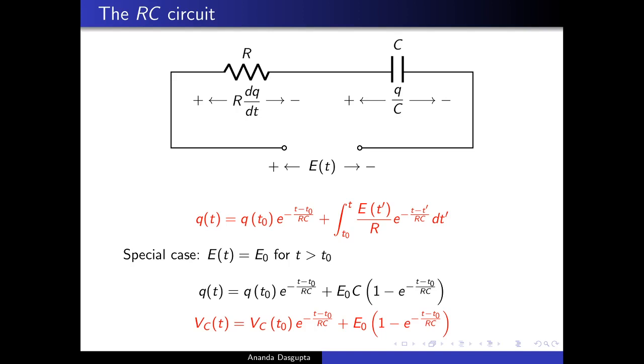There is no further current in the circuit, simply because there's no drop to be had any longer across the resistance. And this is consistent with the fact that the capacitor no longer charges up or discharges, and you have ended up with a constant voltage across the capacitor in the long run. So this is the steady state which this particular circuit achieves in the long run.